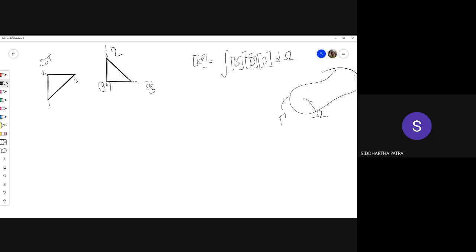And of course, you know that gamma is the union of two subsets, gamma t and gamma u. Gamma u is where we apply boundary conditions, and gamma t is anything that is not gamma u. And the intersection of gamma t and gamma u is a null set. It means I cannot constrain the object over here and also be applying forces in the same direction.